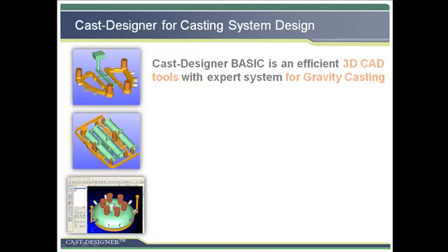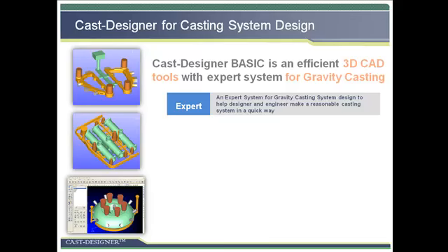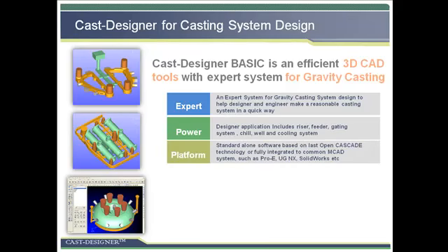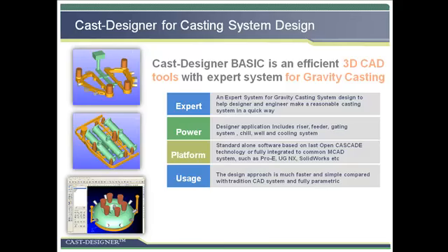Cast-Designer is an efficient 3D CAD tool, with an expert system, specially designed for the gravity casting process. It is an expert system for casting system design, to help designers and engineers make a quick design. The design application includes riser and feeder, gating system, chill and cooling system.